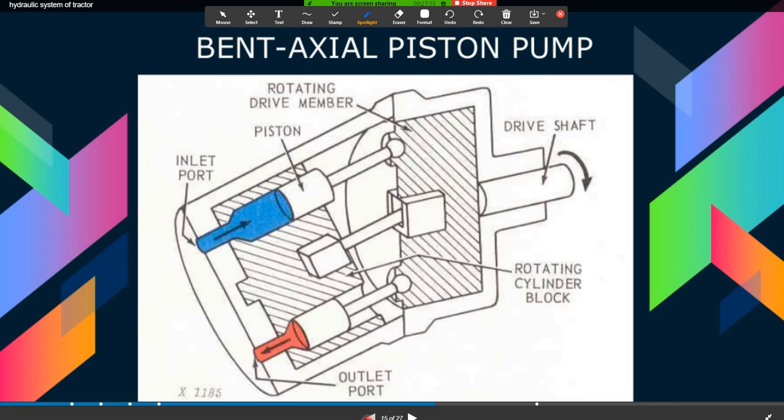It consists of two piston yokes which ride on cam blocks over the eccentric on a camshaft, with two pistons on each yoke reciprocating into opposite cylinders called valve chambers, and each chamber having inlet and outlet valves and springs front and rear.